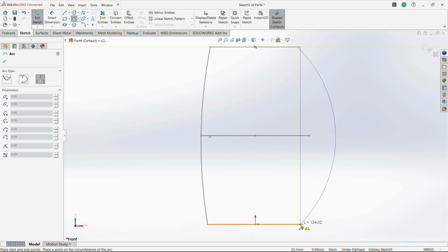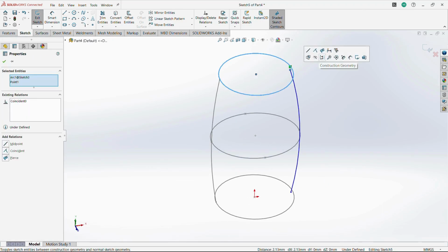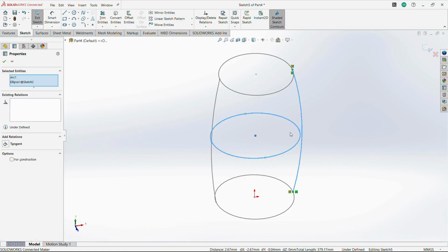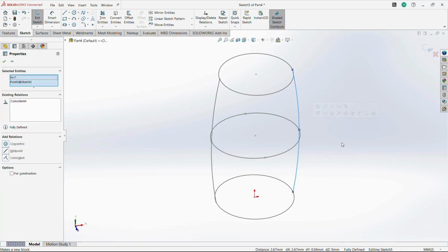So what we are going to do in this portion is create another open profile at this opposite end. Draw a 3-point arc to close the two opposite portions. One is using a pierce constraint. Next, another one using a pierce constraint to close it on this opposite area. Then make it coincident with this ellipse profile at the center of its portions.